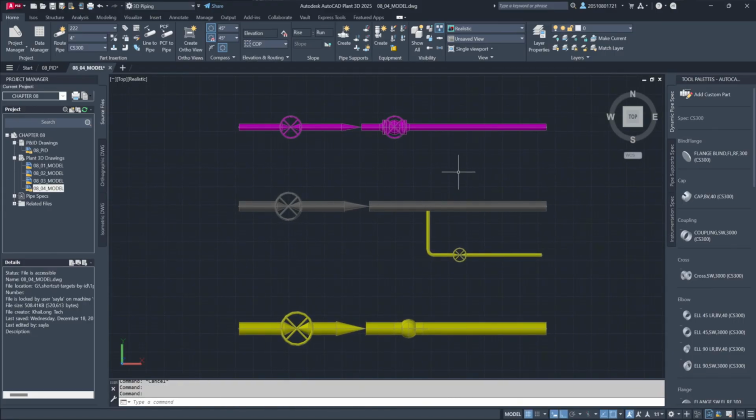Remember, the P&ID is the master document and should be considered correct. The link between the P&ID and the 3D model is not bidirectional to prevent designers from unintentionally altering the P&ID. The program identifies discrepancies, but it's up to the process engineers and designers to decide which document is correct.